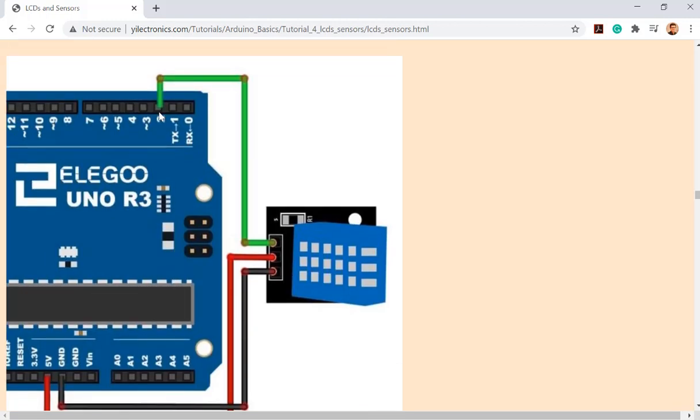So pin 2 is a digital pin, so it's doing a digital reading from pin 2. So the problem is, we are thinking this sensor is doing an analog conversion, or the output of the sensor should be an analog signal, but eventually the output pin of this module is being shorted to the digital pin on the board. So why is that? Any thoughts?